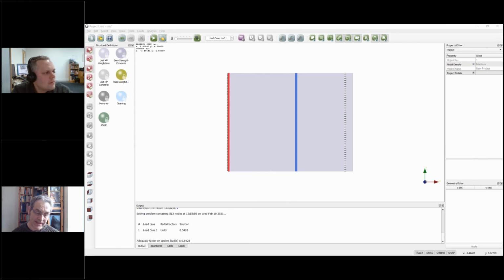Now, in the case of existing structures, you're in a better place in a way, because if you're concerned about serviceability deflections, you can actually apply some load to one or more parts of your building and actually measure the deflections and see if it's reasonable. And very often you will find that the actual deflections are much lower than you might expect. I mean, partly the concrete's been there a long time,